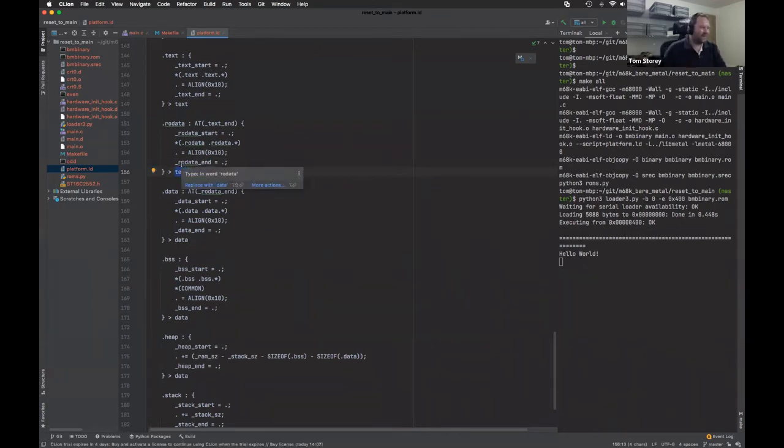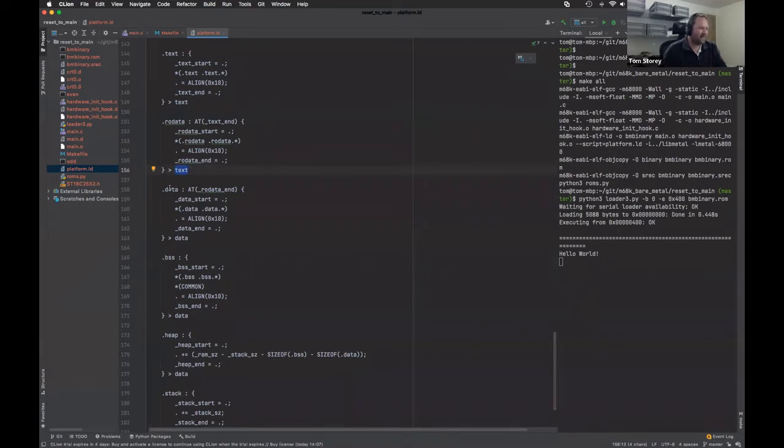So this looks a little bit confusing, but basically what this is saying is that when you have static variables with initialized values, those initial values need to be stored somewhere so that when the application starts up, it can load those values into those variables. So we're telling the linker, allocate a position in the RAM where that variable is going to live, but then store the initial value for it in the ROM after the RO data section.